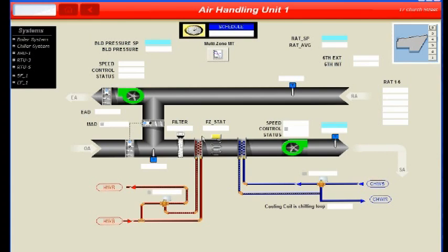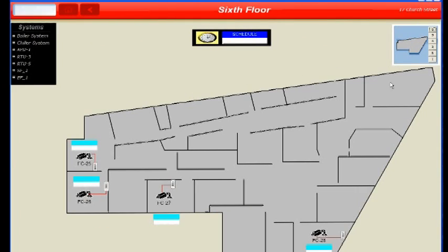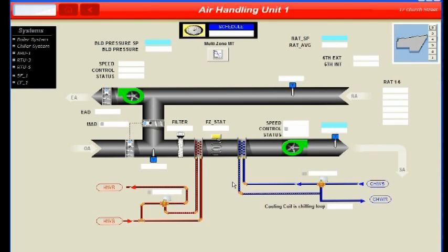As long as your heating coil was off, you could actually use that heat. You could bring more fresh air into the building and allow that fresh air to hit your coil. As long as that fresh air is colder than the actual water temperature by a few degrees, you'll gain some heat off of this. Then again, you'll be sending cold water back down, and if the system on your floor plates is requiring any cooling, these fan coils would turn on their cooling coil valves and take that cold air, which is sitting at between 14 and 17 degrees, and heat it back up and send it back up to the air handler, and the air handler would resume it.